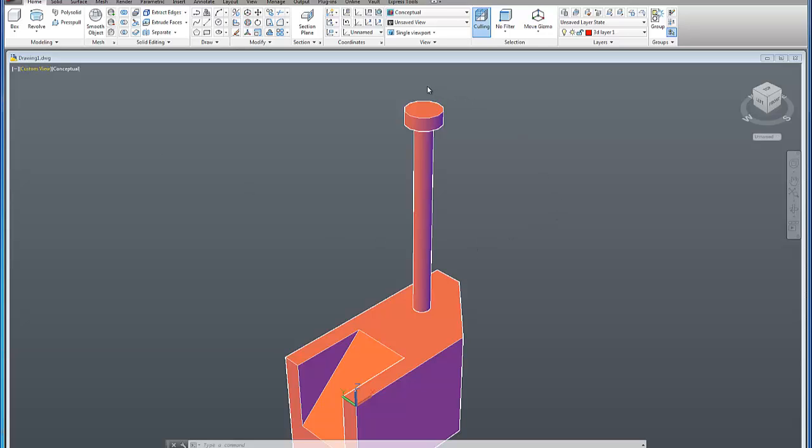As you can see, the representation of the bolt is pretty standard. It looks like a bolt. It actually represents the whole component that we're going to be removing. If it was a countersunk, I'd have an angle up at the top. To actually position it, I'm going to need to draw a construction line on the top surface. What that requires me to do is put the UCS on the object.